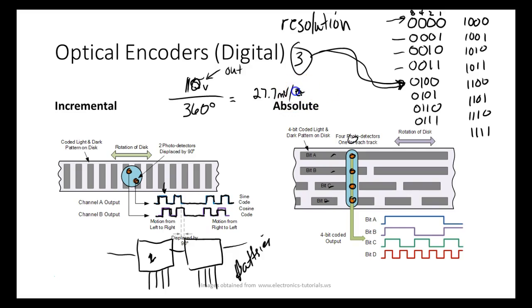Per degree, Rich. So now if I'm getting 5 volts out, I would multiply it by that, and it would tell me the actual angle that that thing was at. We could just as well say 10 volts equals 360, right? You understand? Or we could say, okay, 7 inches equals that number right there. And then I could calculate the scale of the transfer function so my display displays 53 inches, right?